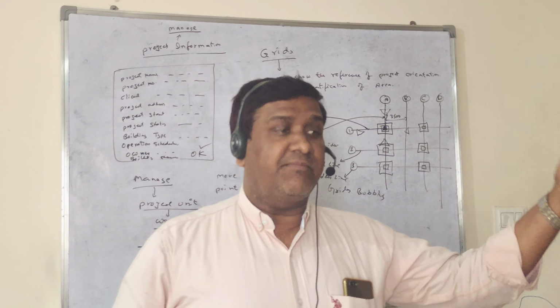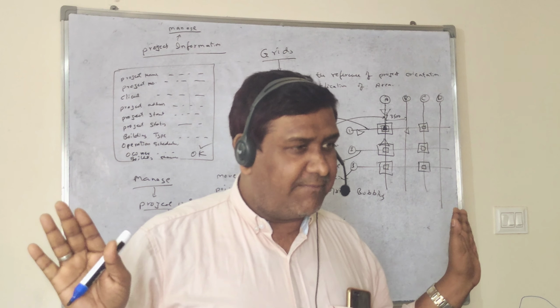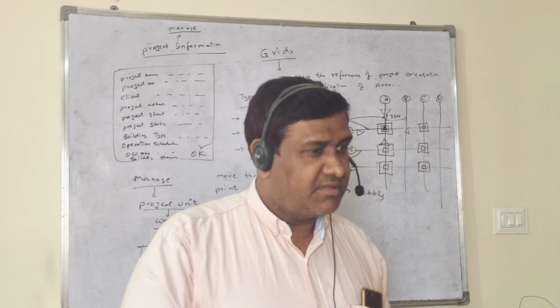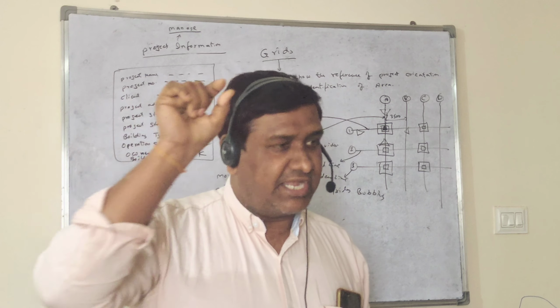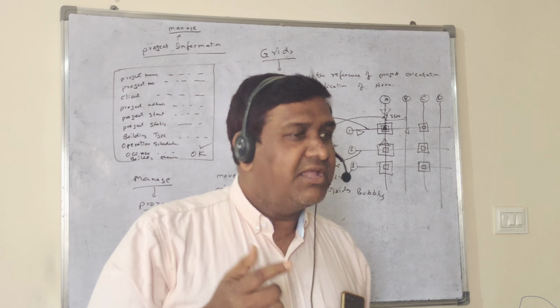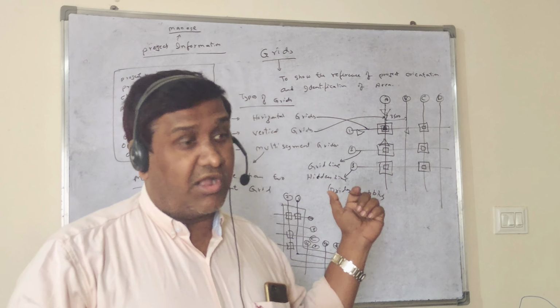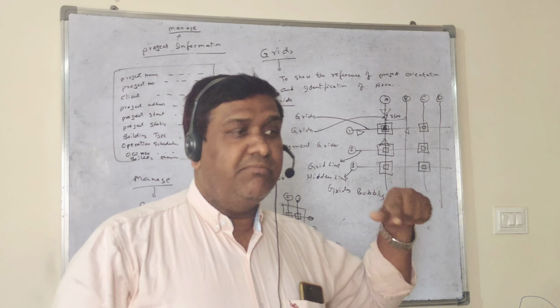But when you go for the presentation, if the client is asking, no, I don't require mm, I require meters, then how will you do it? Because you already kept the dimension in millimeter, but the client is asking for meter. So at that time we have to go to these project units and set the units from millimeter to meter.